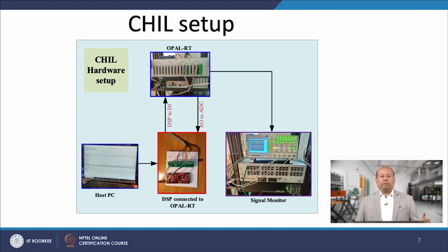The necessary parameters will be called out into the console to verify the control logic for various parameters. The EPWM terminal pins present in the TMS board generate PWM pulses, which are connected to the Opal RT through digital input pins provided to it to drive the converters.